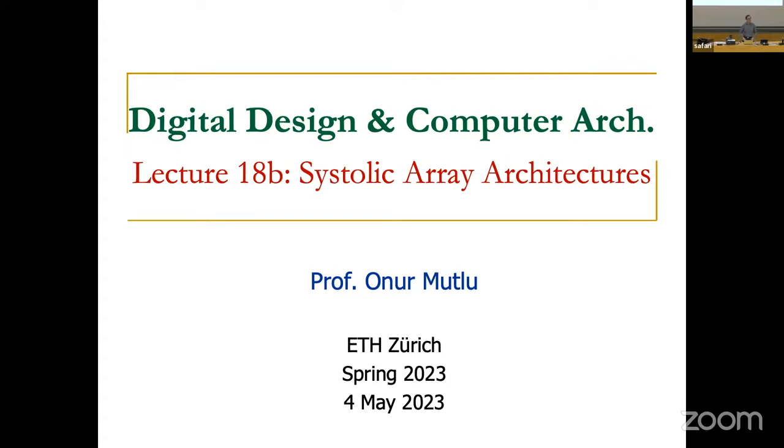So VLIW took a bit later than expected. Let's see if we can finish systolic arrays today. But now you know the concept and you know its impact. I actually believe that VLIW is a concept that needs to be re-examined, especially within the context of these new machine learning models. I believe with the use of sophisticated machine learning models, you can extract more parallelism through the compilers. But that's something that needs to be seen, of course.